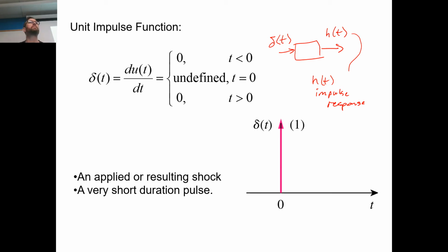It could be the most complicated signal you could think of: add a bunch of sine waves together and then multiply it by a square wave of some other frequency and then shift it up and down and left and flip it around. Whatever the signal is, however complicated it is, if you know what the impulse response of a system is and you have a recorded copy of that, you've measured it somehow, you can calculate how it'll respond to any signal.